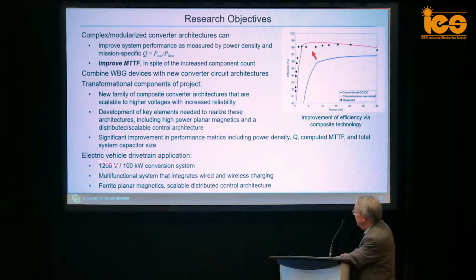Okay, and so we're working on this now in a 100 kilowatt electric vehicle application in the main drivetrain that does both conversion of the main powertrain power as well as using some of these composite converter modules to integrate charging. And we're developing planar magnetics for these kind of power levels so we can run our devices in the hundreds of kilohertz range.